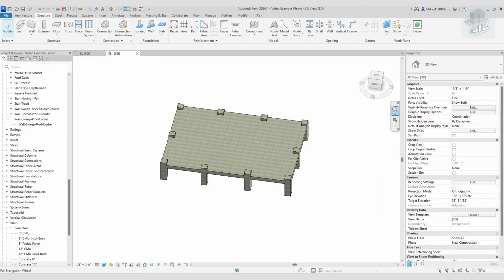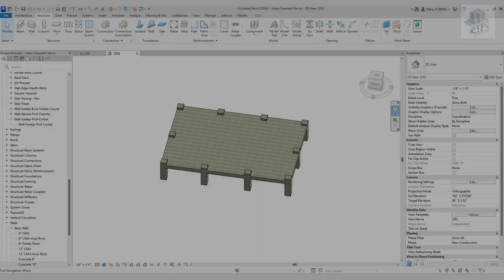In this video, I'm going to talk about structural foundations. In Revit, structural foundations are system families, which means they can't be loaded into a project the same way a standalone RFA family can. Instead, any additional footing types must be brought in using the Transfer Project Standards tool, pulling them from a container project that already contains the foundation types that you need.